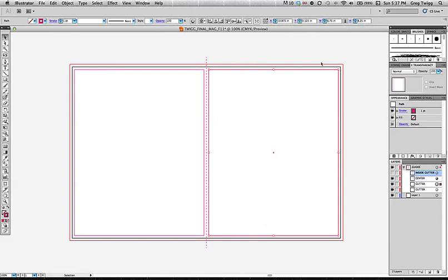But in the event that it is not appropriately placed where it should be, I should be able to do the math, saying that the top right corner, this reference point, should be 1/8 of an inch away from the end. And this is a 14-inch document, which would mean that it needs to exist at 13.875 inches where my X value is. So I got lucky. It's just right there because snapping was on. But the coordinate value needs to be 13.875.